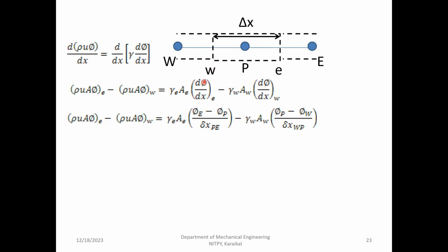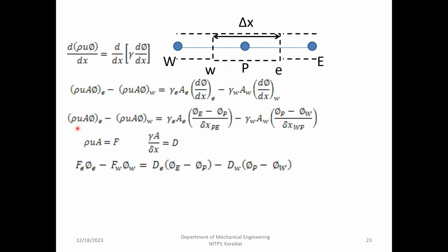So now, the values are going to be stored in the cell centers. I'm going to be calculating the pressure, temperature, and velocity at the cell centers. So how do we determine the property at the wall? For that, we can have multiple methods. This will be termed as flux, and this will be the diffusion term.